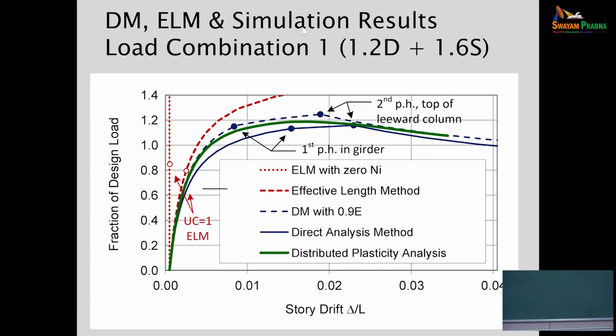And I actually skipped this here. The white dots on the effective length method, these points, are where, if we're doing the so-called unity checks, the evaluation of the verification, we got to 1.0. That means we've reached the strength check. From elastic design, we don't allow any further load.